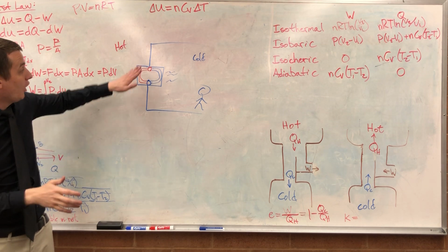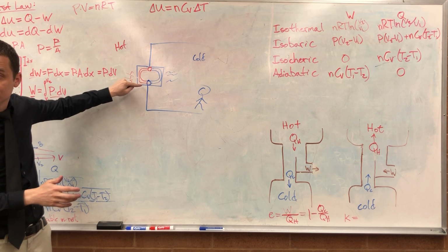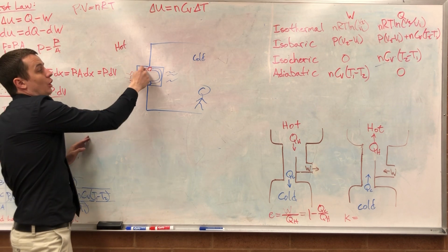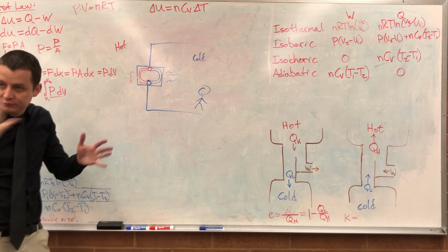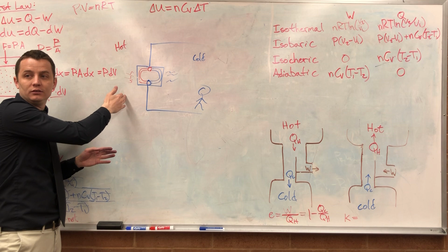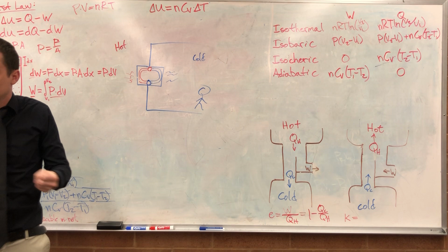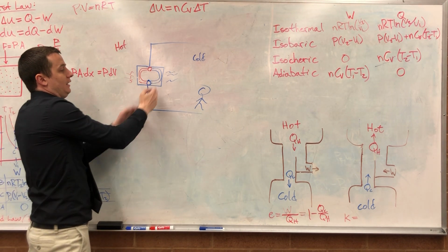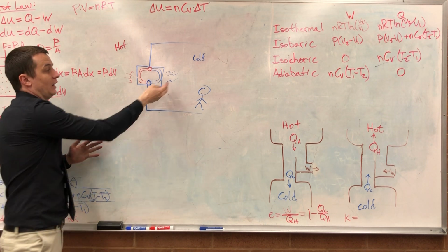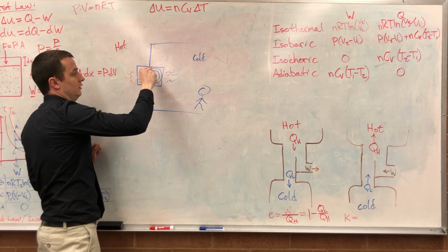And so now it wants to give off heat. Over here, the liquid is giving off heat because it's been really compressed. You have some air flowing through the system to help get as much heat off of it as you can. That's why it's blowing hot air out here. Then there's some regulator, and once it goes past that, it's able to expand again. So it comes inside, and now that liquid is able to expand. As it expands, it needs to absorb heat. So it's going to suck heat out of the air around it over here, and then dump it outside, and then round and round it goes.